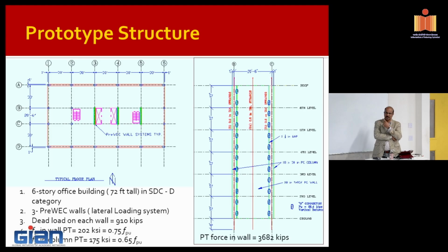So in this case, 3 walls, all 3 identical. They are cantilever type walls. Construction is easy. Post-tensioning is easy. Energy dissipation, you can manipulate those things. Hybrid frames, you've got a lot of moment columns. How many bays do you have? You've got 1, 2, 3, 4, 5, 6, and with 6 times on both sides, you're looking at 12 connections, and then you have 6 stories. So they add up. And then maintaining quality control, every connection has to be done properly. If you give them a choice, they prefer the wall.